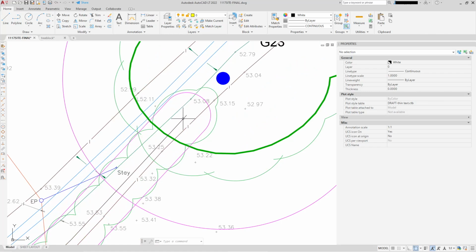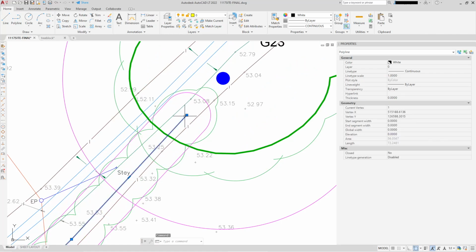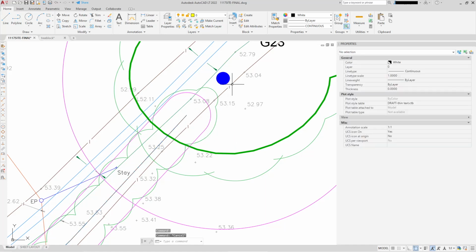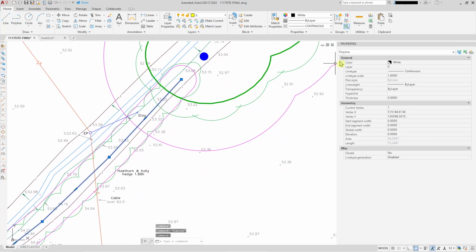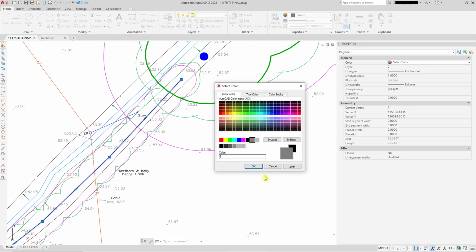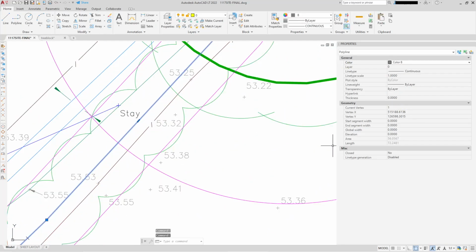And this line, centre line, will become my sort of category line to show the centre line, and also to show the category of this hedgerow, because I don't want to colour the RPA or the canopy to represent the colour. So for instance, let's say this is going to be category C, so I want this to be grey, and I want to give it some width to make it stand out a bit.